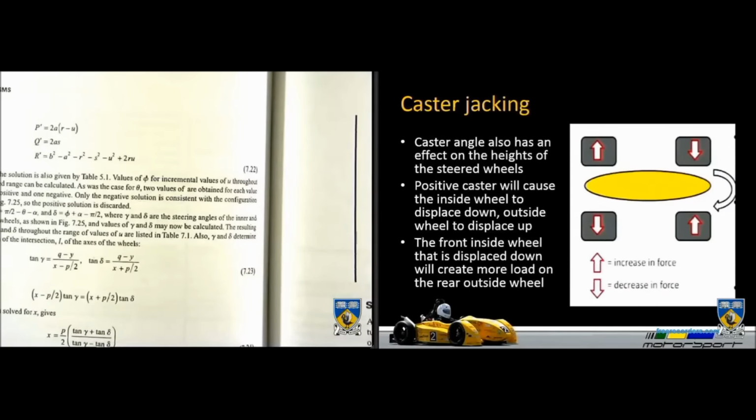As you turn the wheel, it tilts the wheel into the ground and pushes down harder. Through reactions in the chassis, which I might talk a bit more about on Wednesday, it pushes the opposite rear wheel down to the ground. So if you're turning right, for example, your front right wheel is pushed harder into the ground, pushes your rear left harder into the ground, and can lift your inside rear. Go-karts are really good to see that.